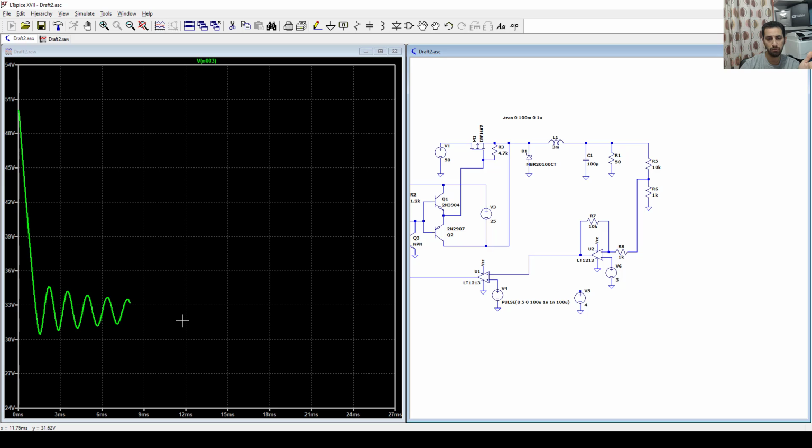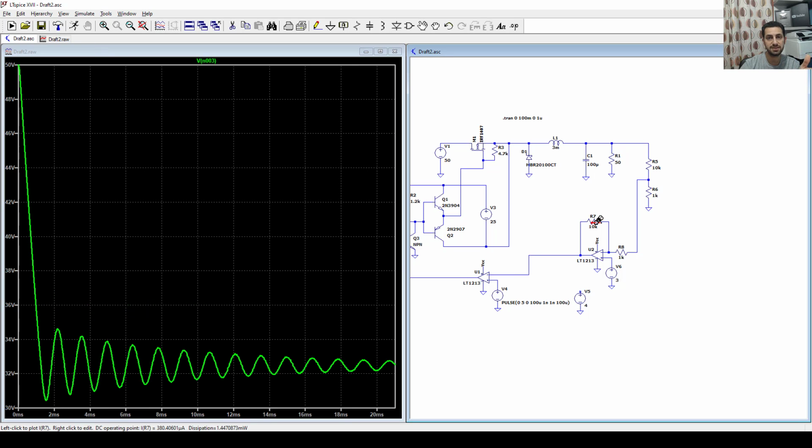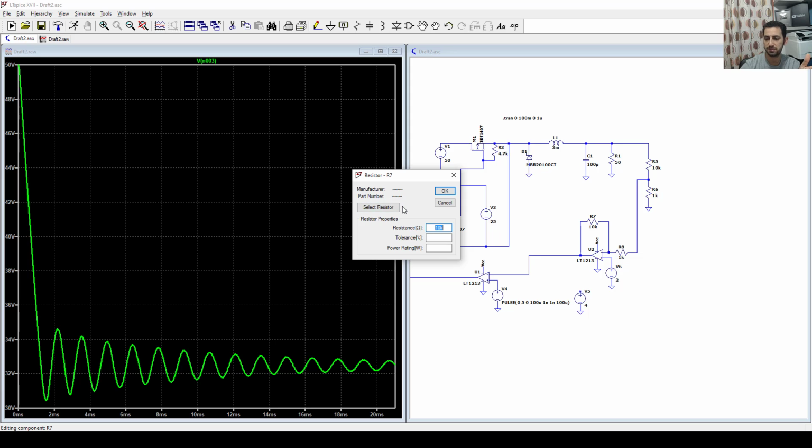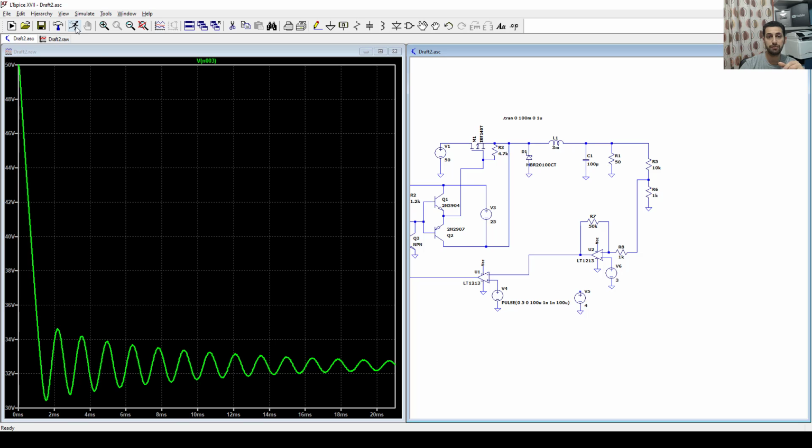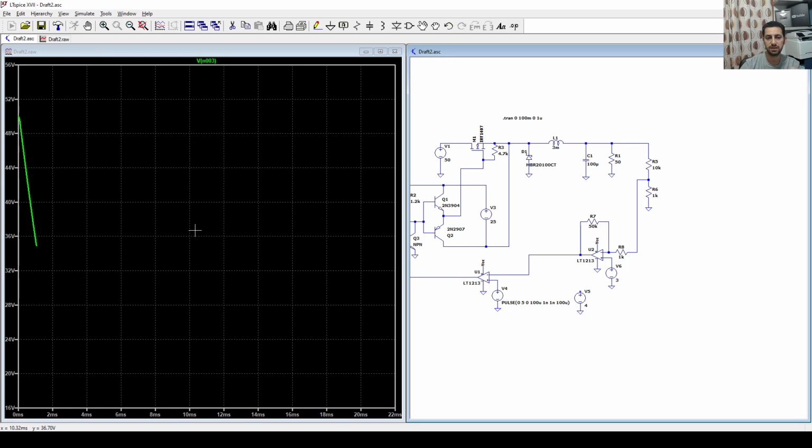Okay, so now within 15 again it damps, maybe within 20. So now why not increase the gain? So 10 kilo here, let's say 50K. So we have a gain of 50. Make sure that you don't destabilize it. And I think more gain will destabilize it. I think we now have this destabilized.